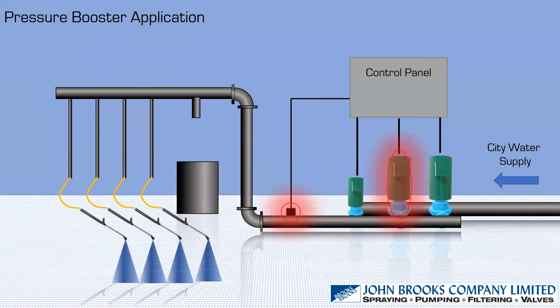And then it would go offline and we would then bring on one of these larger pumps that could then try and maintain a certain pressure. And again, that VFD is taking signals from the pressure transducer and varying the speed, trying to catch up on itself. There could be a PLC as well in there.